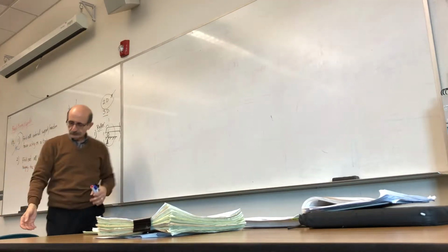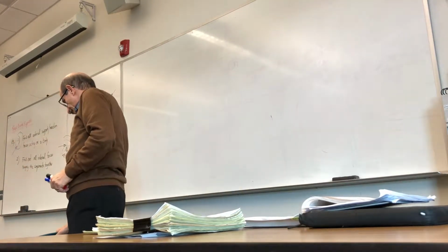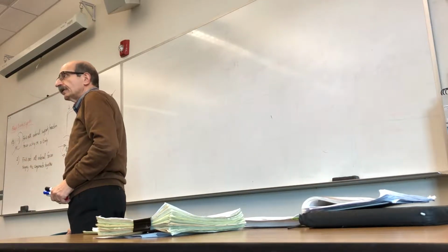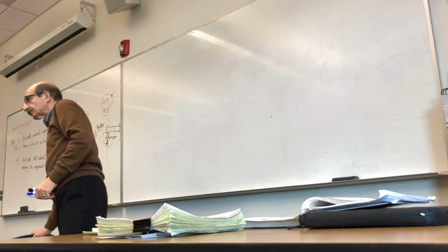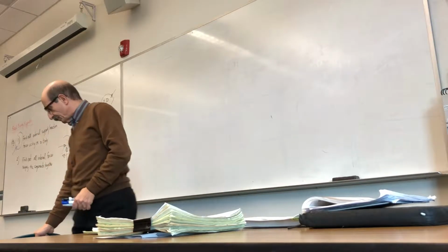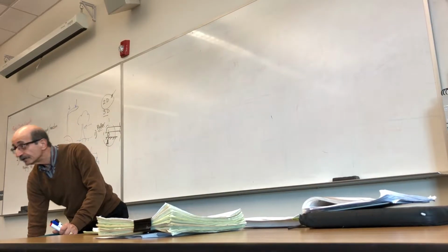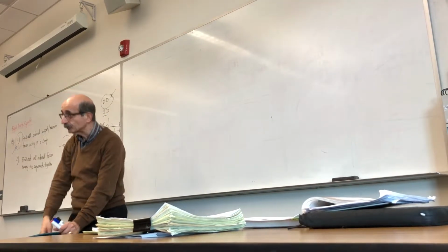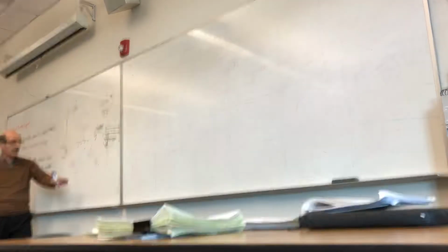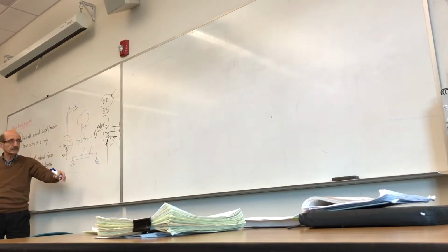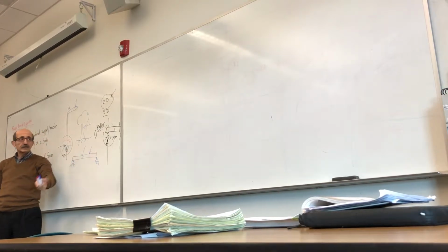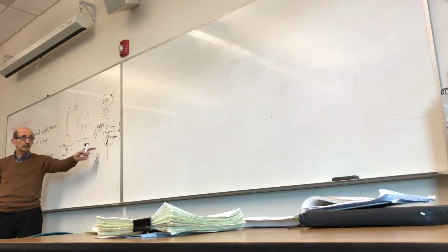So assume this is a 2D structure. Okay, motion is allowed in this direction. Motion is also allowed in this direction. You can rotate it if you want, okay? But when you sit on it, you cannot move this downward. So the mechanism that is supporting this structure is allowing motion in any direction, but resisting motion in one direction. So that support represents one unknown force.